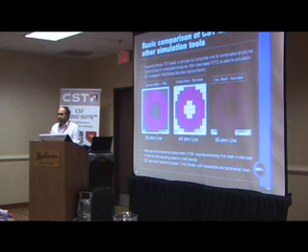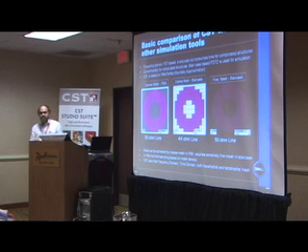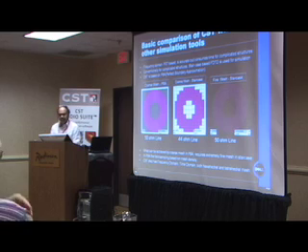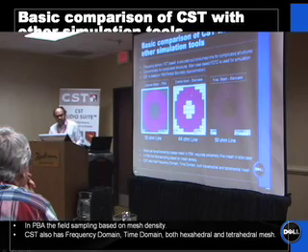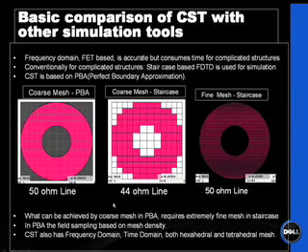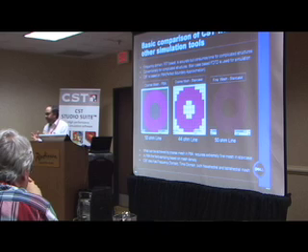So one way to make a quick and reasonable approximation is by using a staircase method like XFDTD or SEMCAD. It is a reasonable approximation, but sometimes it's oversimplified. Just to give an example, this is a coarse mesh 50 ohm part. When you apply the staircase method using a coarse mesh, it gives like 44 ohm. That is a 6 ohm error.